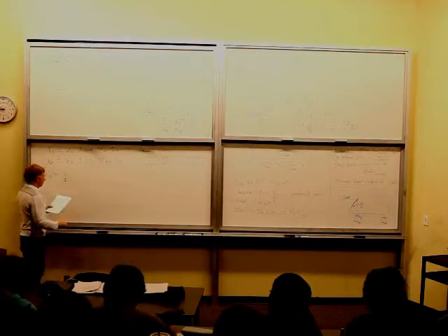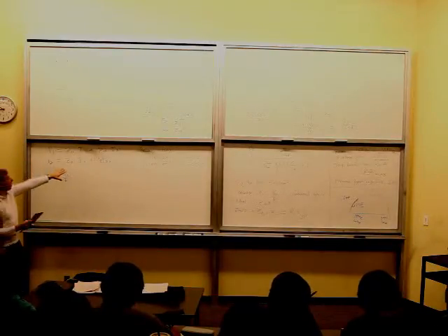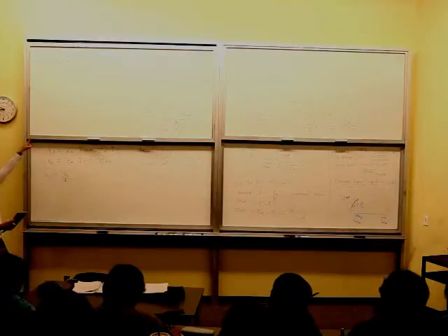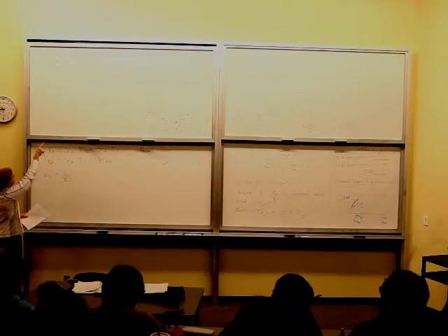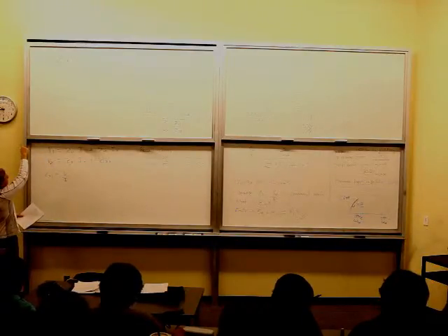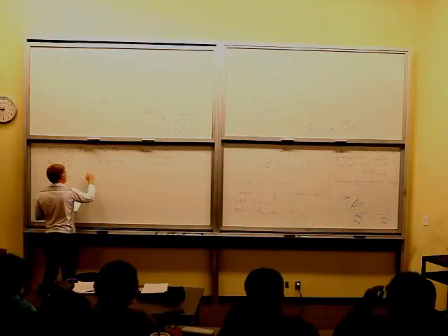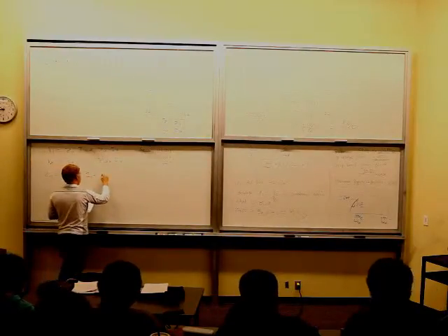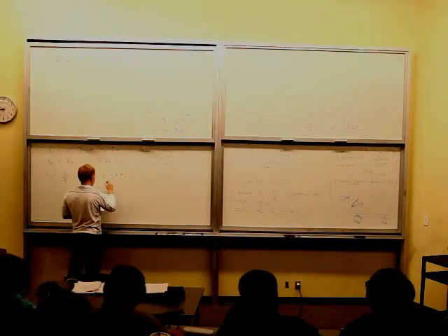And what I can say here is that I2 is off, right? We already said I2 equals 0. So I know that that dependent source is going to be 0. But let's write it out explicitly. So what I can say is the current going through that resistor is going to be V1 minus that voltage there divided by R1. So that's going to be I1 equals V1 minus V times I2 over R1.